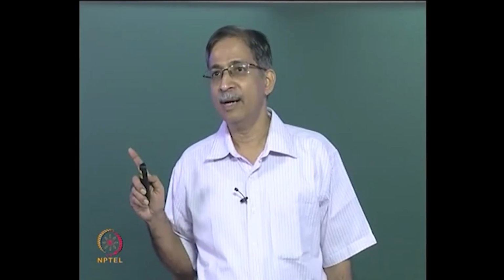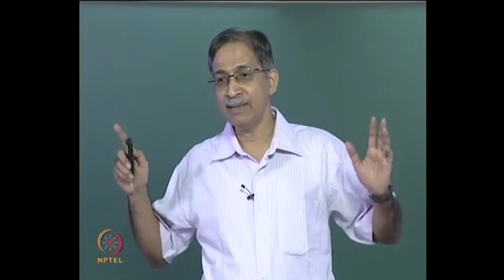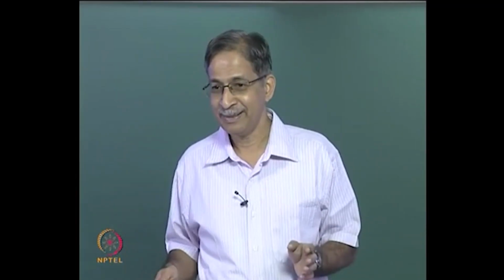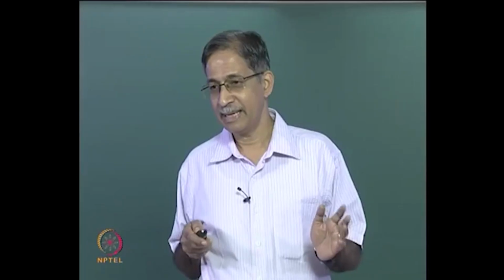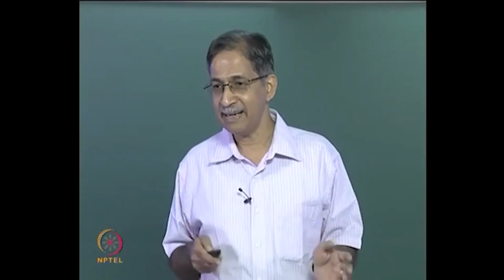Okay, so I hope up to this stage you know how to do it. If you write the full K matrix, you can't fit it into that slide because the size is 12 by 12. So it makes sense to do it KAA, KAR, KRA, KRR.